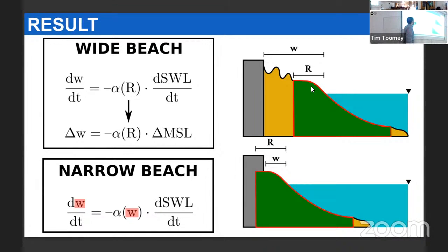But the constant of proportionality is again this ratio of the width and height of the profile, but it should be computed using average conditions, not the extreme ones. So sometimes the ratio of the profile will be bigger than the average, and sometimes it will be smaller than it. But in general, the actual rate of erosion will be that given by average wave conditions.